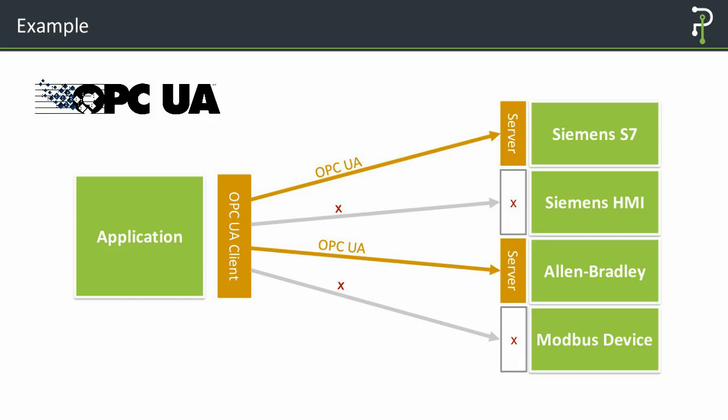On the other hand, one of the downfalls I already said is the market share, and the other downfall is that OPC UA, due to this richness of the protocol, brings a lot of overhead. So OPC UA is nice if you poll every second, for example, for some status values. But if you have, let's say, a motor running there and you want to monitor the current of the motor with 10 milliseconds, then OPC UA is not a good fit. As the protocol is just too big or too verbose, then you might prefer to use the native protocol, which is what we do with PLC4X.